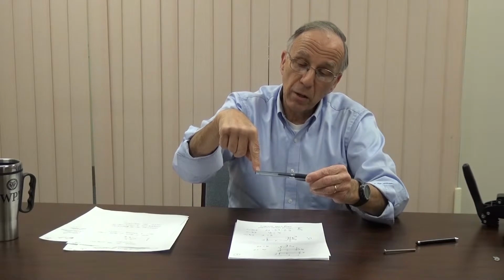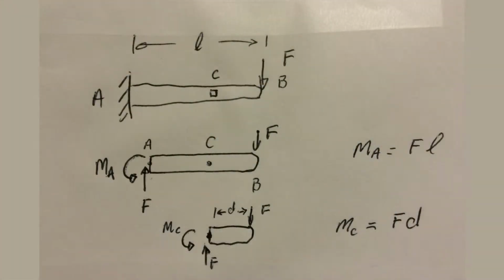However, if we look at putting the load here, I have the equal and opposite force going up, but I also have to exert a moment using my hand to equilibrate the moment, which in this case is clockwise, caused by loading here.